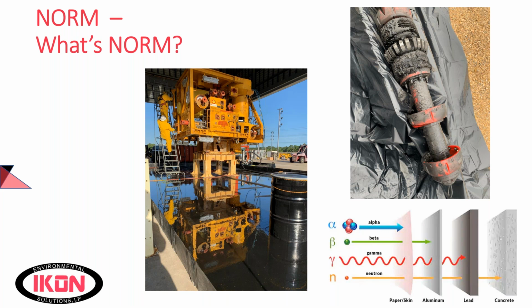As I said, when you pull the produced waters and such up, when you have the uranium and thorium deposits down in the geologic formation, the isotope or the element that's primarily soluble is going to be radium. So you get the isotopes of radium-226 and 228. As that water starts coming up closer to the surface and the pressure decreases, you start getting all your pipe scale deposits, your carbonate scales and other compounds. Those are going to have radium in them. So your radium gives off gamma radiation, which you can detect with a gamma scintillation detector on the outside of pipes. So you can find out just by walking up to some pipes that have pipe scale in and measure it from the outside whether or not there's some radium on the inside of that.